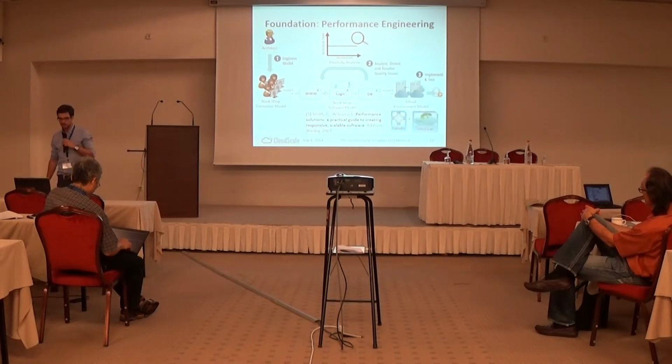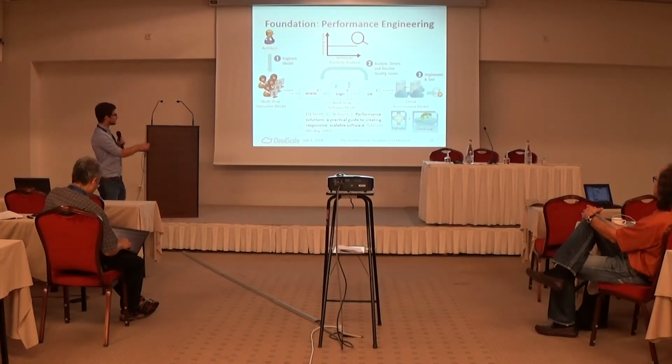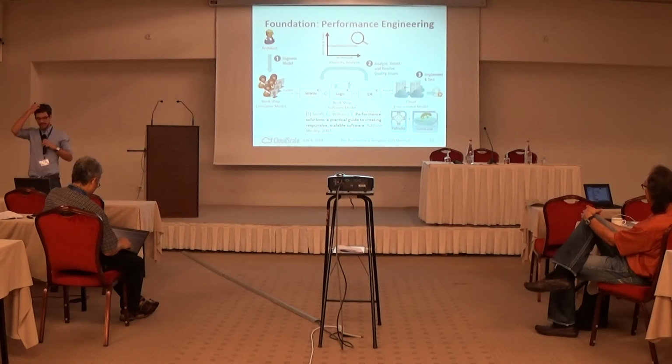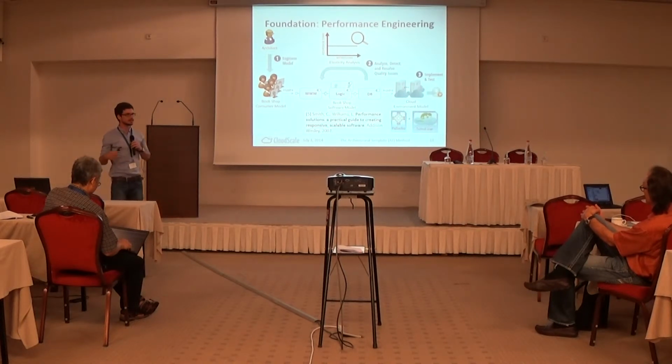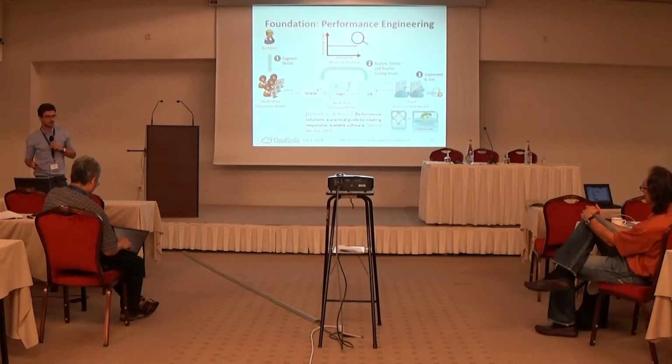There's also some tooling that makes use of that process: Palladio, where I'm one of the core developers. There's also an extension of Palladio called SimuLizar. Palladio is a software simulator. Palladio takes these models I've introduced as an input and can simulate them. And SimuLizar adds the capability to Palladio to model self-adaptations and to analyze them.